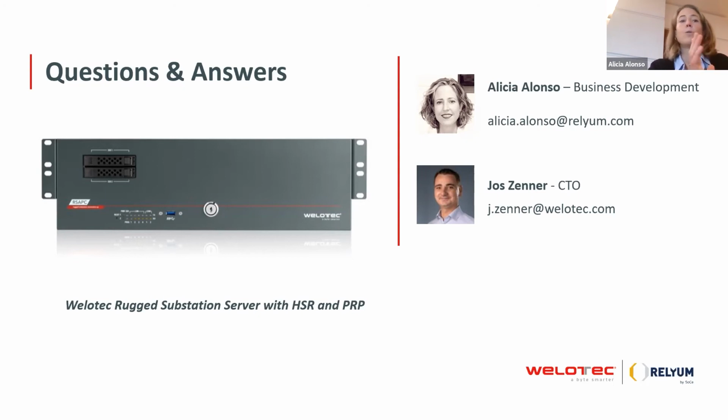Just in case you lose one of them, you need to have the PTP or the GPS receiver in the second one. So with PRP, normally you have two PTP receivers, and with an HSR configuration, only with one, you should be able to receive the supervision frame from the second link, from the second path, in case of link failure.